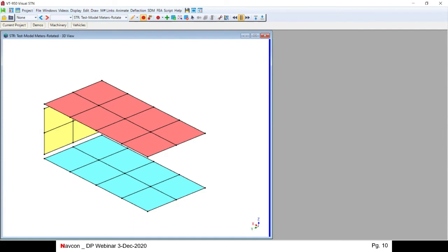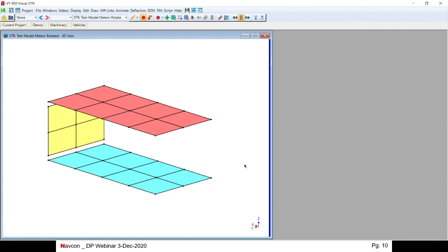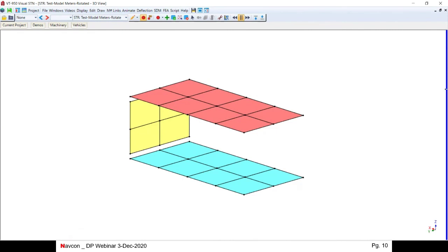Now, let me find my cursor here. This is a modal testing model. Of course, it's much simpler than a finite element model. Most modal tests are conducted with maybe as few as 10 response locations, up to maybe 300 or 350. That would be considered a pretty large modal test. And the modal test model, when you open this up, is basically a stick model.